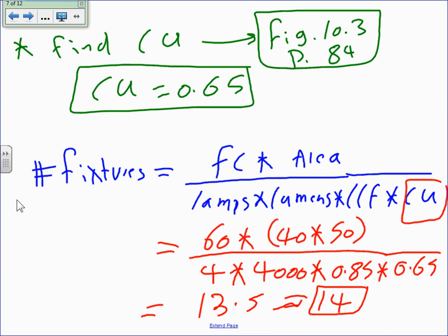Okay. So based on this criteria, guys, and from this figure that you're looking at, the coefficient of utilization for this fixture is 0.65. Can you guys let me know if you know how to find it, Chad? We're good. So for the test, I'll grab one of these Lithonia ones and highlight the fixture for you. The only thing not there is the floor. Who cares? The floor is only one number anyway in this sheet. And you can find the coefficient of utilization for this fixture based on the room cavity ratio, the ceiling, and the wall reflection.